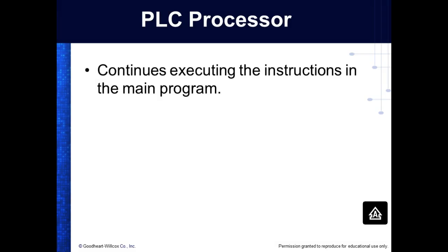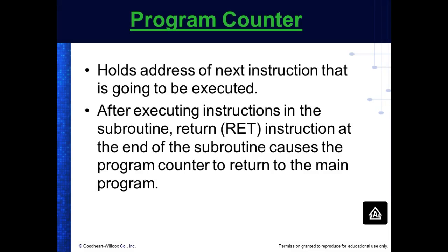So when you ran through the subroutine and you got it where you wanted, then you just teach it. Yeah, and we just retaught that one point. And what was nice about subroutines is you can run them without calling them. If you just run them, they won't leave the subroutine because there was no return address saved. Does that make sense?